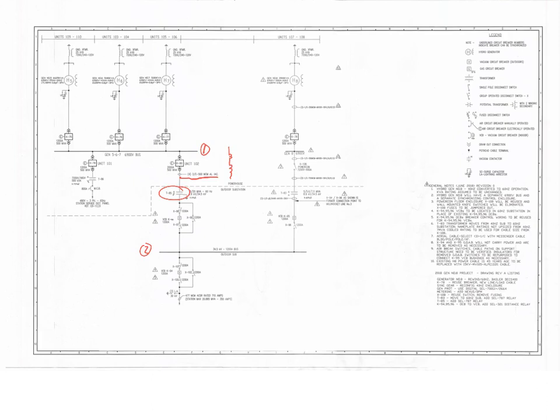Power systems analysis tools don't know how to add impedances in series, believe it or not. So what they do is they just put a bus in there and then just do a regular old Y bus. This is called a tap or a node bus. Essentially, the way a tap or node bus is processed in the applications that you're using, it does exactly the same processing as a regular bus. It just doesn't display the results for the user, the power user essentially. Okay? And in Aspen, you can convert a tap bus to a normal bus just by clicking a box. It's a pretty simple process to do that.